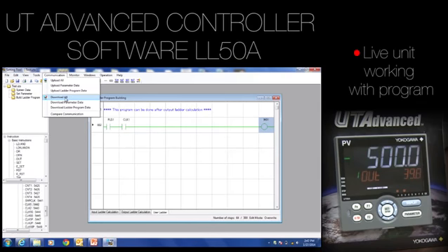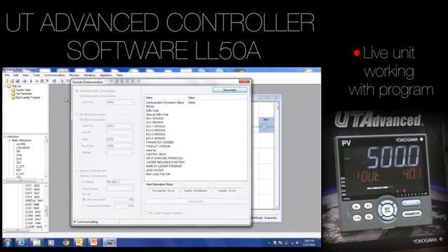The upload and download is a little bit different than what you're typically used to. Typically, most people are used to when I finish a program and I'm going to send it to the controller or to some external device, I'm going to upload. Yokogawa has done this differently. It's actually a download. So we're downloading from our PC to, what I like to think of as, the lower level device or the controller. So just be careful with that because it is a little bit confusing.